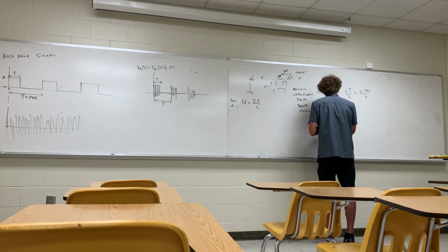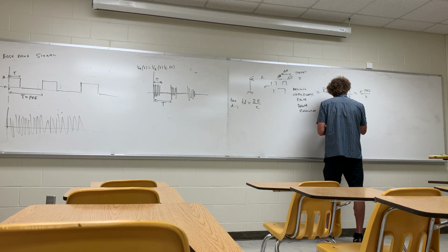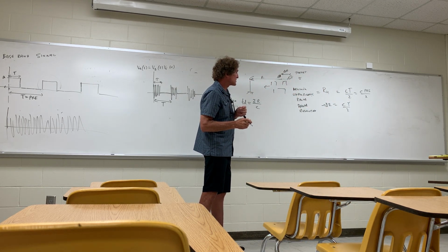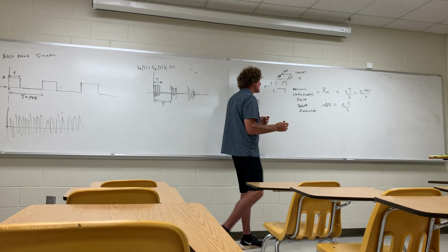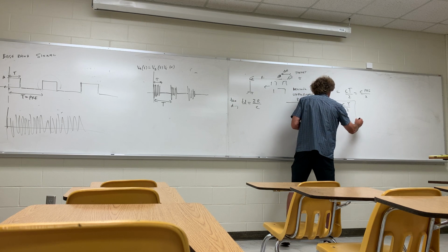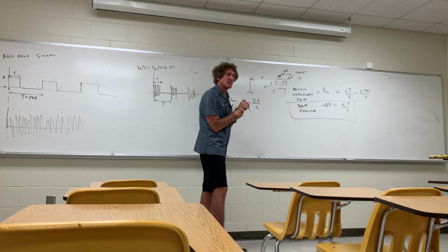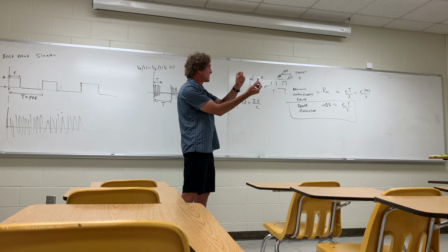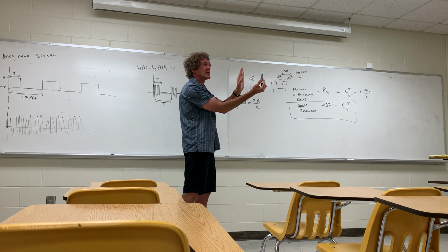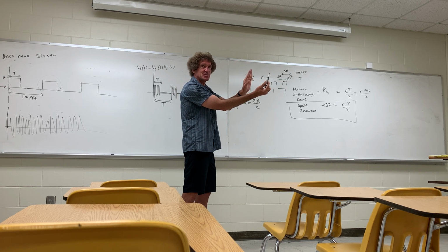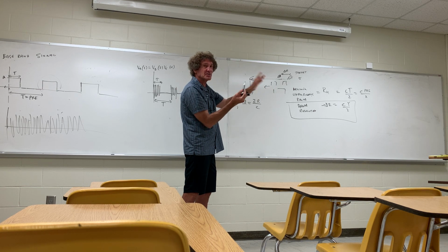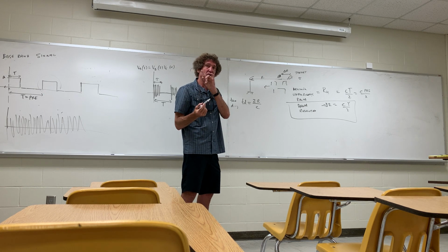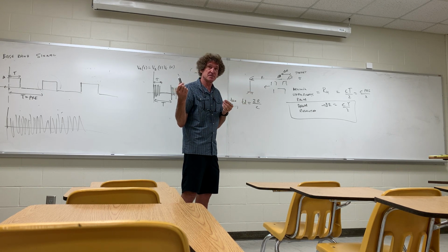Delta R itself is equal to C times tau over 2. Almost identical to maximum unambiguous range, but delta R is the range resolution. And it's simply C tau over 2. You can play a little game, and you can take snapshots in time, increase the time, and see where the actual amount of space is where the waveform occupies, with two targets. As soon as it gets larger than that, you get two distinct returns back. But when it's anything smaller than that, you only get one return, and you can't tell if there's one or more targets. Y'all follow me?